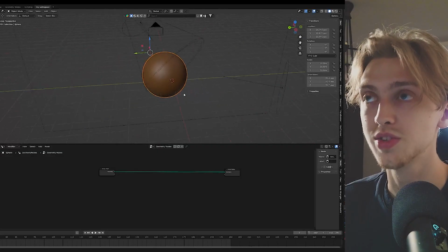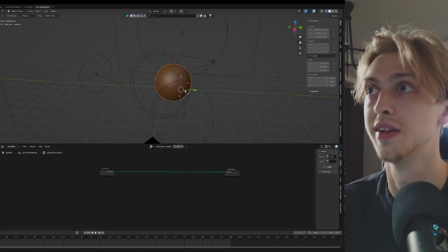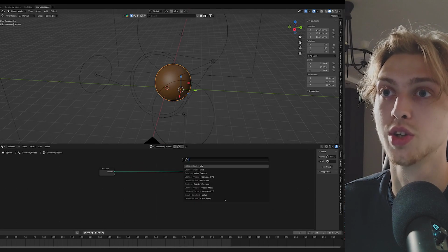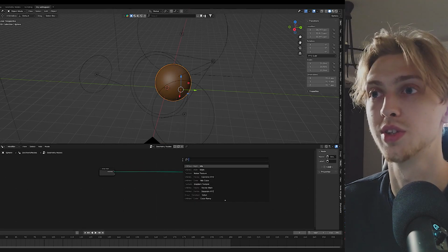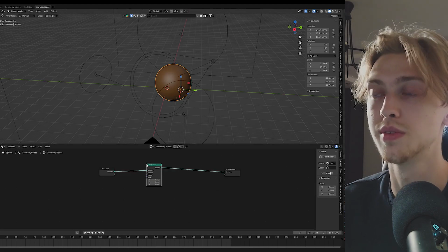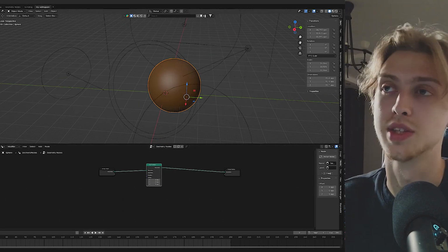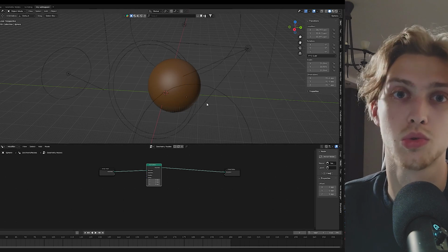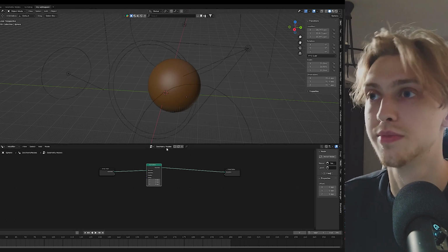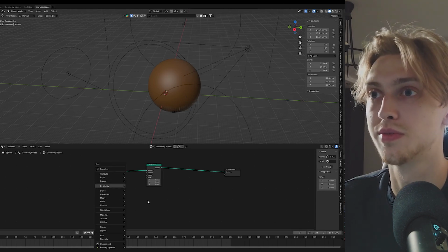So for this we need to create a UV sphere using Shift A. Next you can apply the subdivision surface to it. Then we add the geometry node editor and create geometry nodes. The first thing we will create is the set position. This is necessary so that we can simulate the swaying of our bubble as it happens in reality, meaning that some air currents affect it or its own weight. Let's make a set position and place it between the input and output.